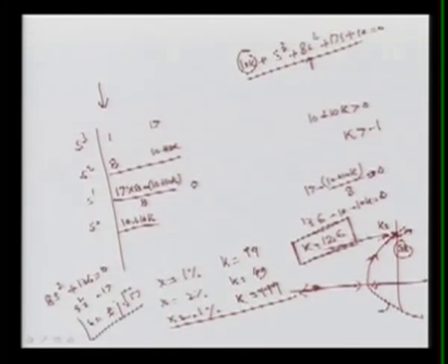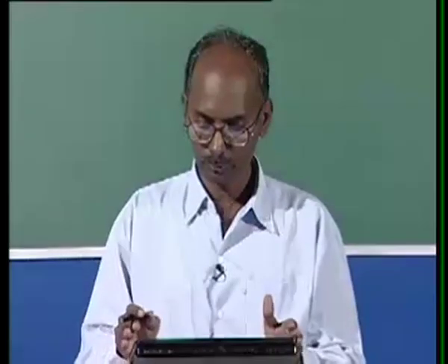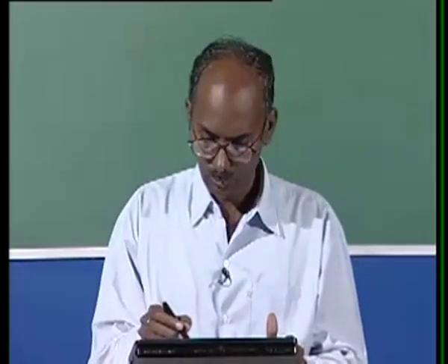So we are getting the values of s is equal to plus j under root 17, and here it will be minus j under root 17. So we got the root also, we got the gain also, and then we saw that both are contradictory to each other. So let us see now overall, that is your root locus plot.